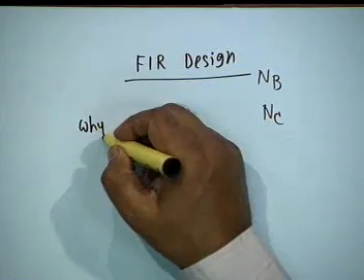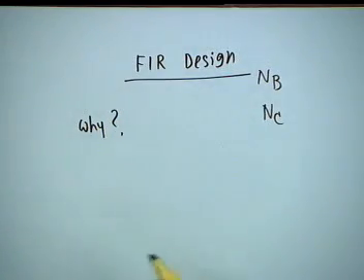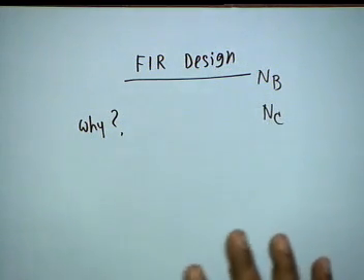Even then, why should we use FIR? If the filter design is so uncertain that at every step you have to go back and ask yourself, am I proceeding in the correct direction? Have I taken the correct order? Have I taken the correct procedure? If that is so, then why should you use FIR at all? Unconditionally stable is one. Linear phase, that is of utmost importance.